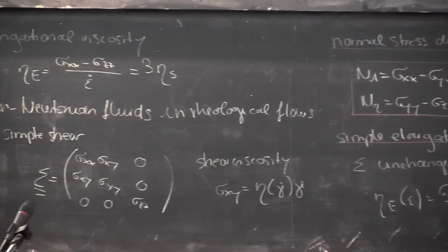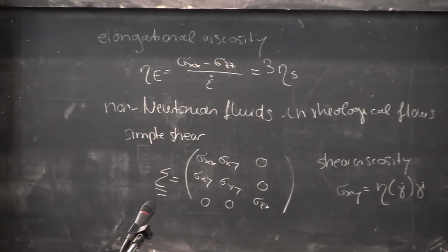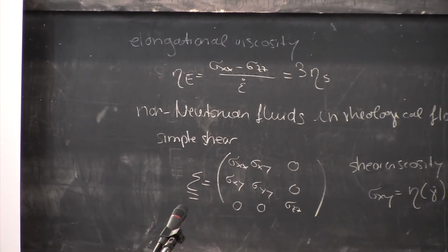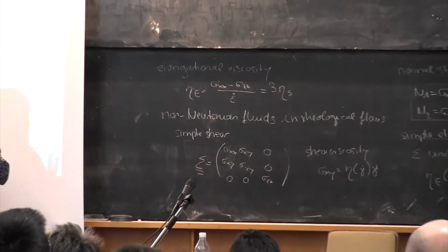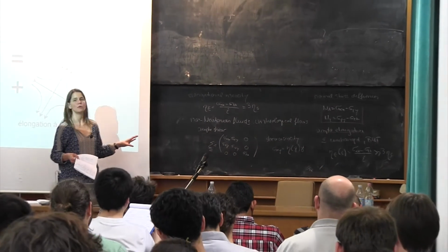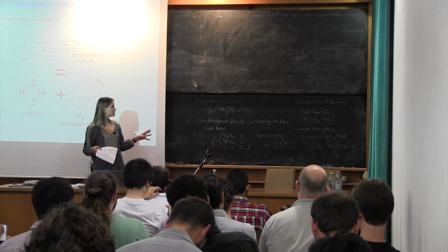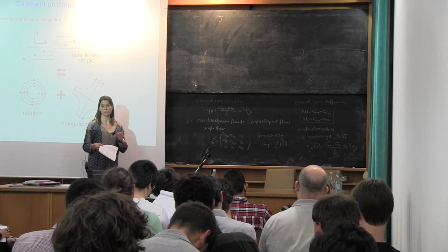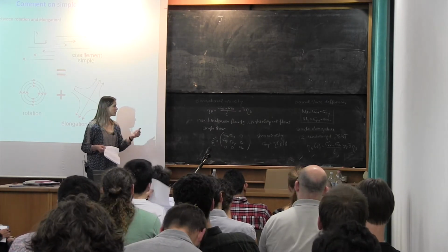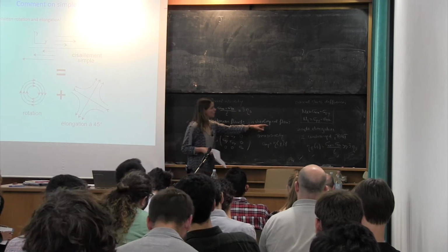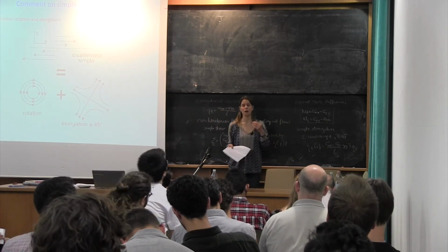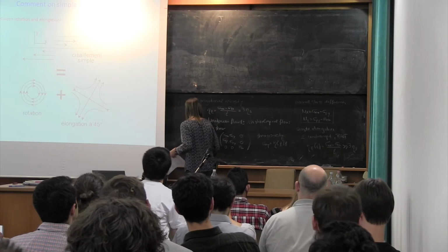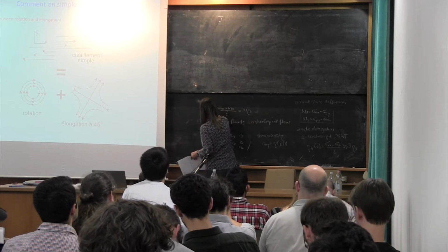Okay. So this was the introduction to the main non-Newtonian properties that we have already encountered a bit over the last days, but this is how they are defined. And in summary, what you should keep in mind is that the stress tensor now is nonlinear. There are dependencies of all of these properties on the shear rate, and it becomes anisotropic. So let me just write this down.